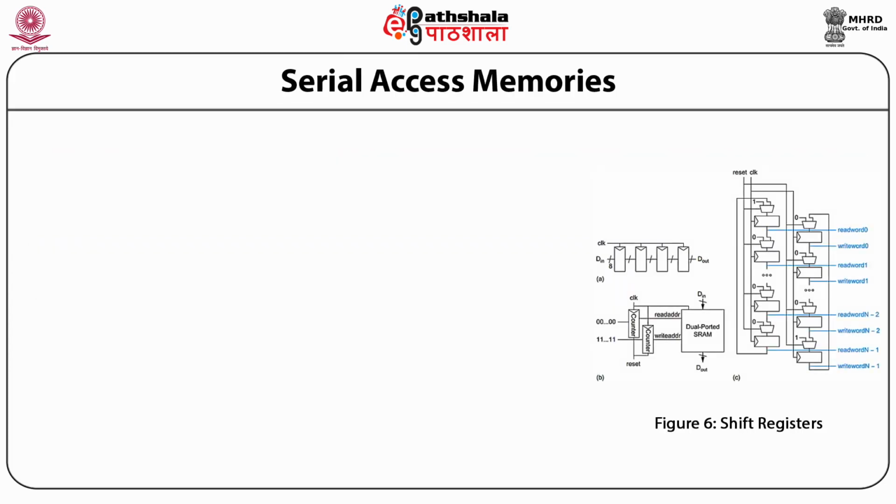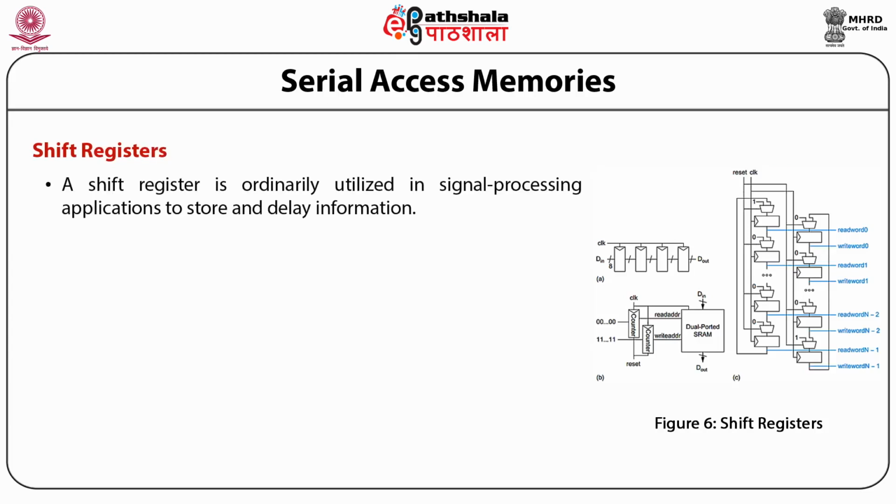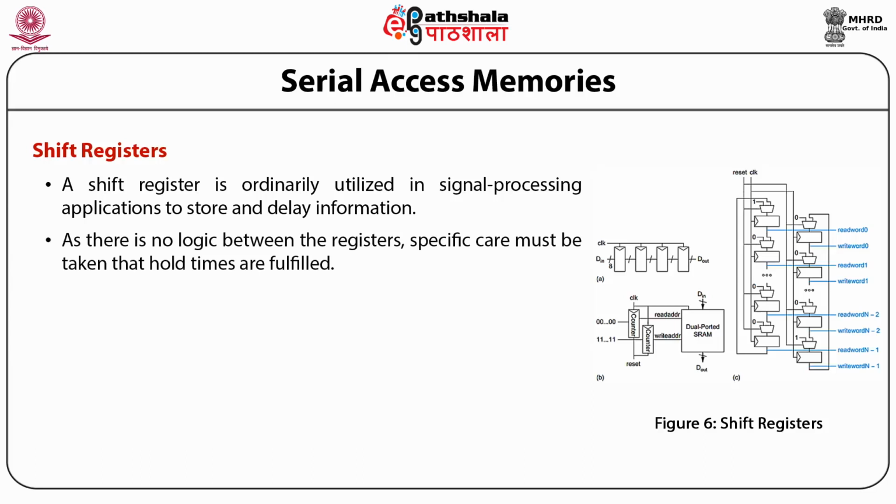Now let us discuss shift registers. A shift register is ordinarily utilized in signal processing applications to store and delay information. This figure A demonstrates a basic 4-stage 8-bit shift register constructed from 32 flip-flops. As there is no logic between the registers, specific care must be taken that hold times are fulfilled.